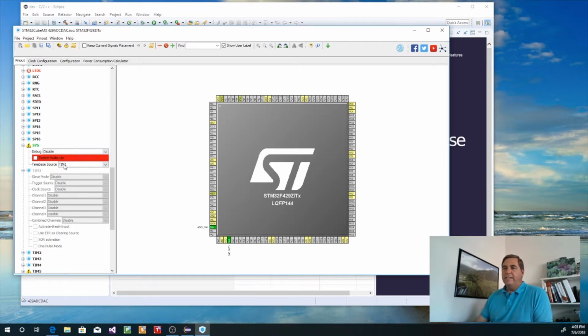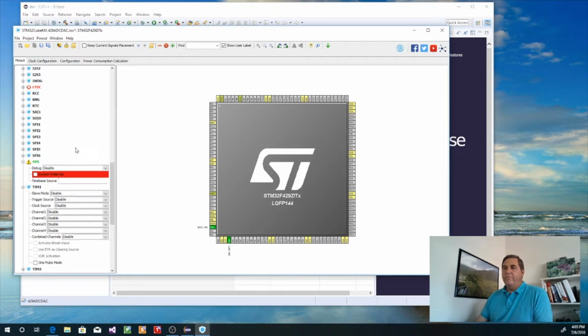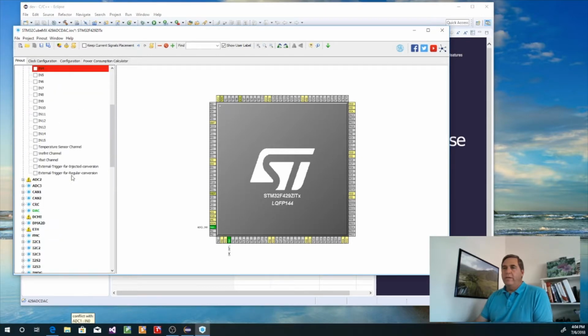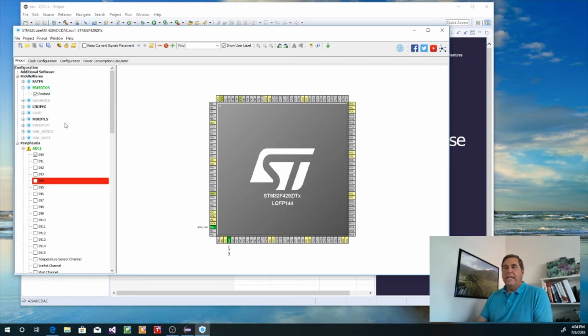So when I selected this timer, if I set SysTick, I'm going to have trouble. It's not going to work. So I come down here and set timer 1. And when I do, it's actually going to set everything up for me, so that in the RTOS, I have a 1 millisecond timer. And all RTOSs use a 1 millisecond timer because they keep track of time, right? So anyways, that's the only change that I've made in my project.